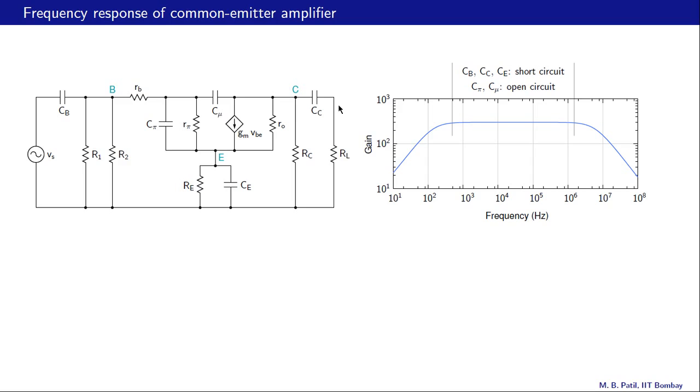Then we go to the next frequency, and so on. And when we have all of these data points, then we plot the gain as a function of frequency, as shown in this example. And we should remember, of course, that the amplitude of the input voltage is always kept sufficiently small so that there is no distortion in the output voltage.